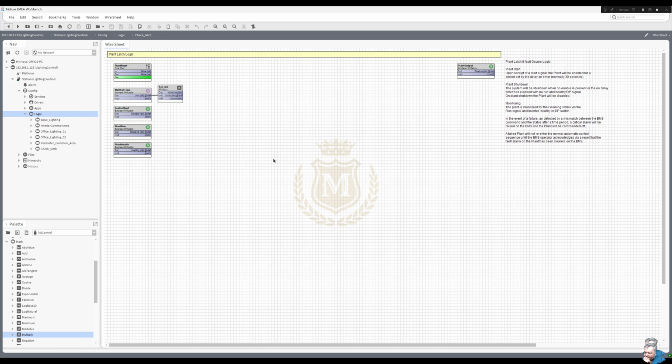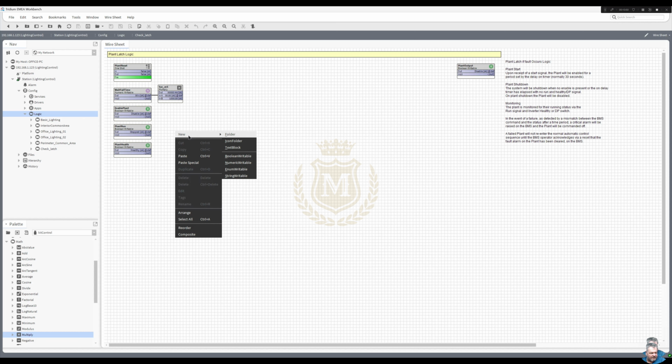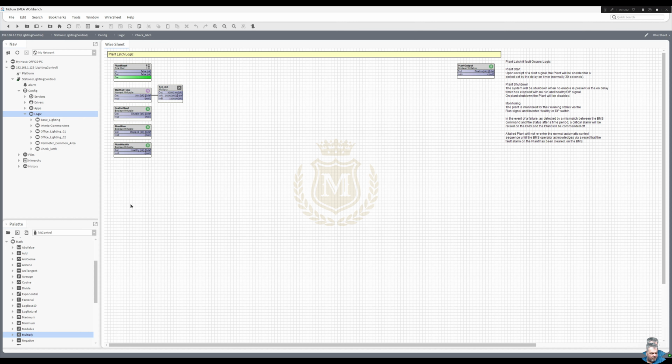So we need an enable and we need the DP, i.e. differential pressure, if it's a pump or flow or whatever, we need some proof to say that the drive is running. So let's do the drive run and the healthy into an AND gate, because it's got to be healthy for it to run. I think we all agree with that.